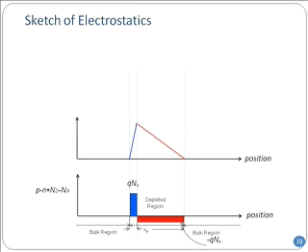And because there is net charge on the other side, negative charge on the other side, once you begin to cross the junction and begin to integrate, this will subtract because there's a plus charge for the blue and negative charge for the red, and this will gradually subtract. And do you realize that eventually when you are at the end of the junction, sorry, this point should be here, then it should be equal to 0.